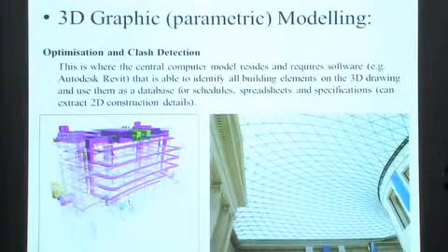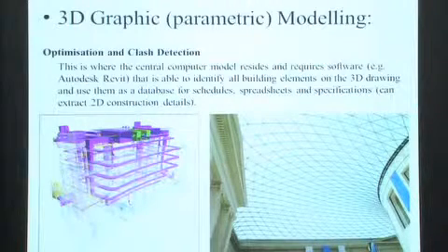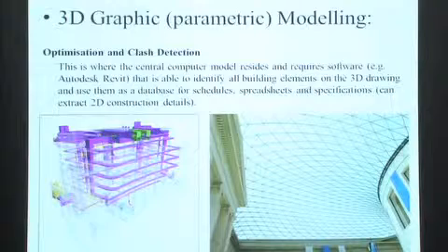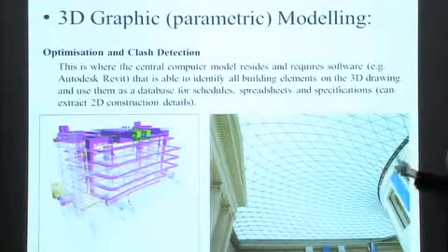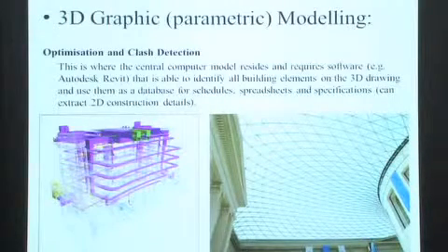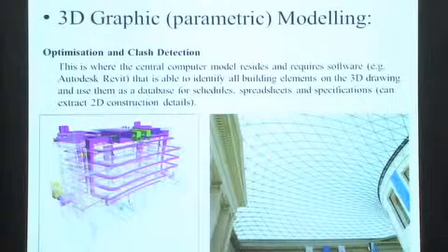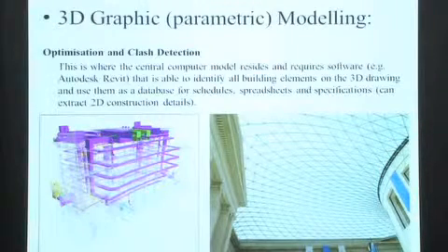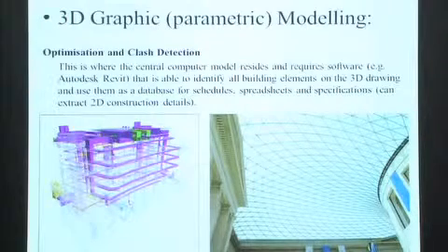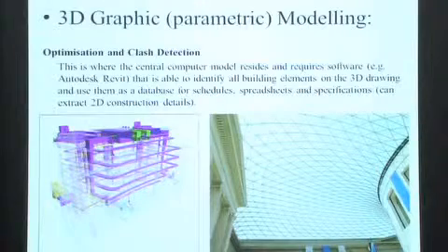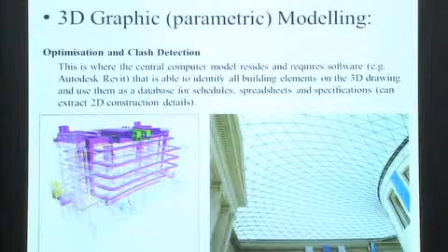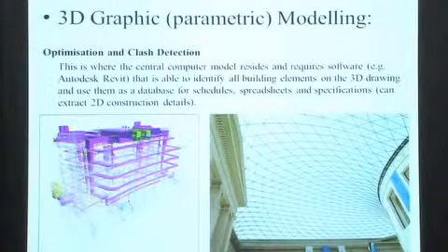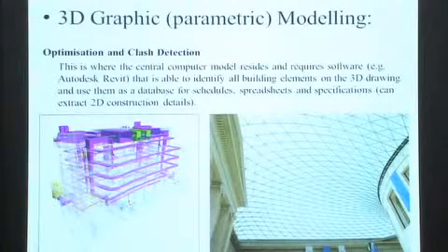And it's the first time that I've ever seen parametric modeling as a computer program, because Arup, I think, devised a program, and I saw it working in real time, where you've got a rectangle, you've got a circle in the middle, you've got this system, which is a combination of tangential and other angles to make the triangles, and you pulled that circle very slightly off-center, and everything started to reconfigure itself around. Now, the optimization was to minimize the variations of triangles. So you're saying to the computer, I want the least possible combinations of triangles, to make the fabrication process more efficient. So you give the computer a set of parameters, you work out the algorithm, you pull that circle slightly off center, and you end up with an efficient parametric design.